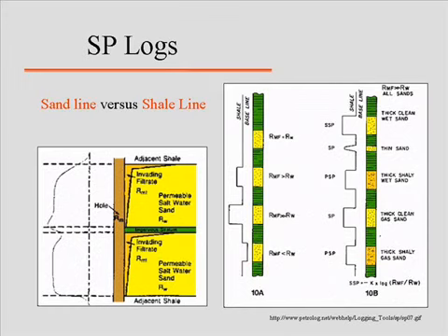You also have to deal with changes in the properties of the sandstones. If you have more porous intervals, you might get more infiltration of drilling mud, and that will change the properties you get for the SP logs in some cases. The shape of the SP log can be used to interpret what type of formations you're dealing with, as well as to start thinking about how those sandstones were deposited, in other words, the depositional environment. That can be really useful if you don't have cores.